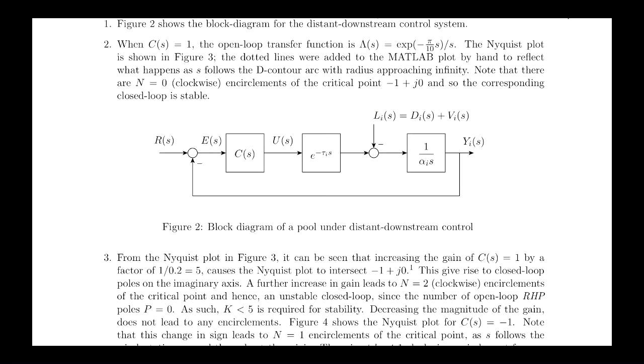As we saw last time, in order to get perfect rejection of step changes in the plant input disturbance, we needed, by the internal model principle, an integrator in our controller. Having one in the plant wasn't enough. Now we're trying to reject changes in the load here, which will be more or less step changes.